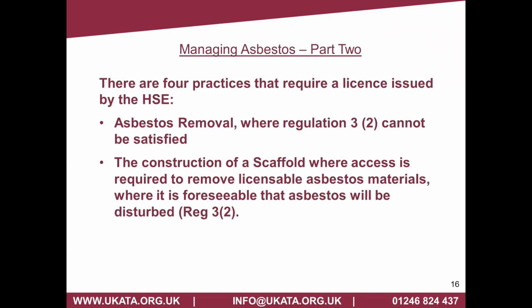There is also, to remind you, of scaffolders. So scaffolders who are erecting scaffold to enable licensed asbestos removal works to be undertaken where, and this is important that you understand this, where it's foreseeable that the asbestos will be disturbed, then they would also have to be licensed by the Health and Safety Executive. So a good example of this would be, where a scaffold is erecting a platform to remove some asbestos lagging, there's a potential that they could damage the lagging, the scaffolder would then need to be licensed, and they would have to go through the same sort of notification, medical record keeping, etc.